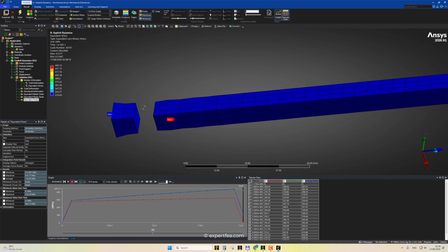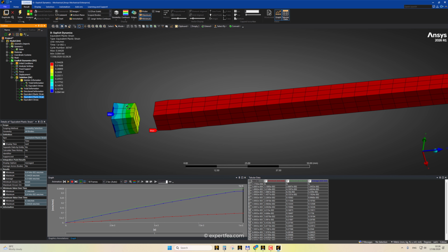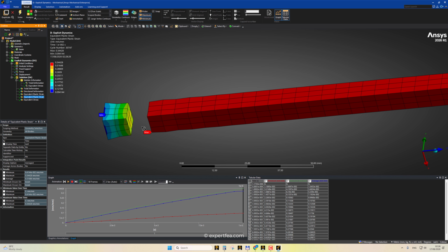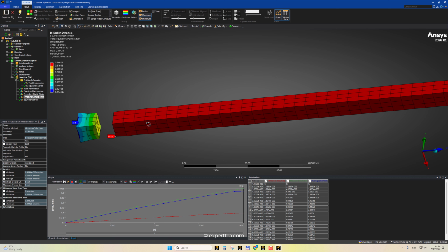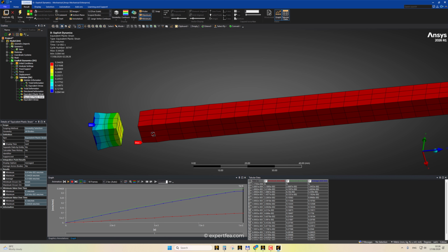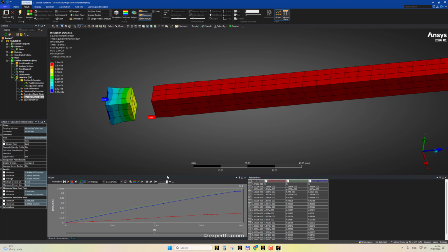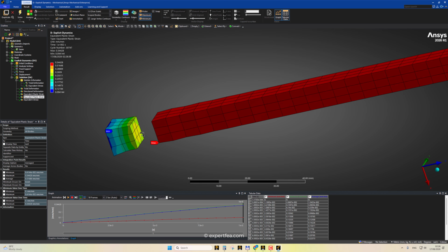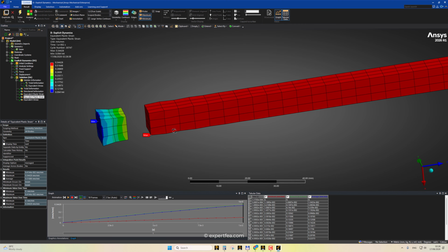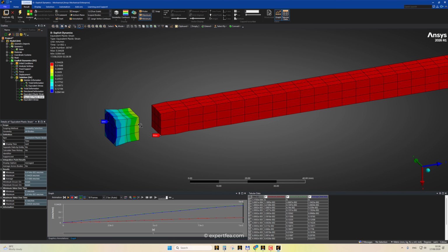This is a very sudden break, and we do not have a clear necking here, and we are expecting a necking. So this material or this simulation is kind of good to impress some beginners, let's say, but it's not very proper and reliable. So it is a start, but it's not the best option regarding the mathematical apparatus and the FEA approach.